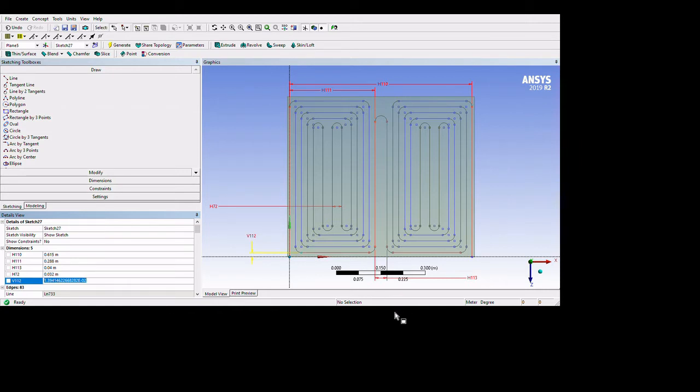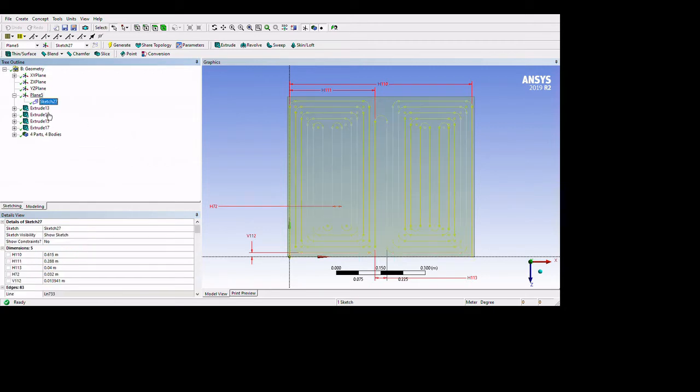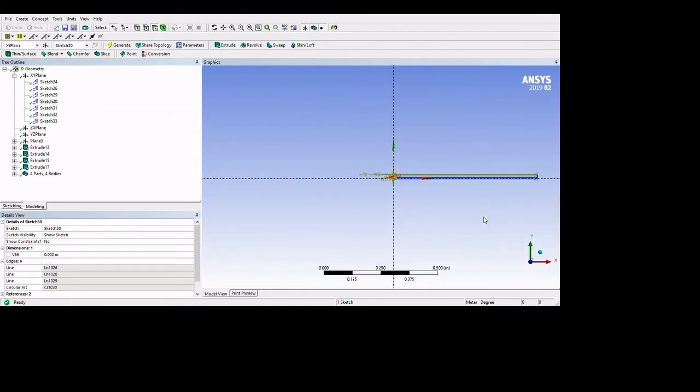And the clearance between, we call the side of the absorber and the bottom edges of the PV panel, is 0.014 approximately. Once we have the absorber loop all drawn, now we can sweep our bodies of tube, water, and thermal paste.